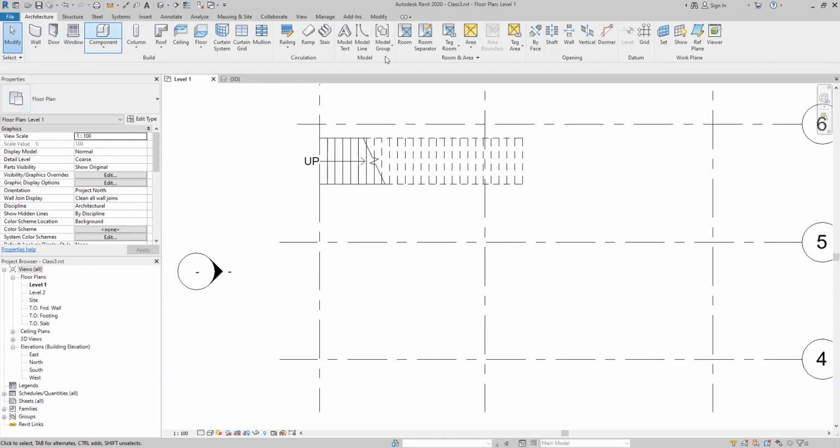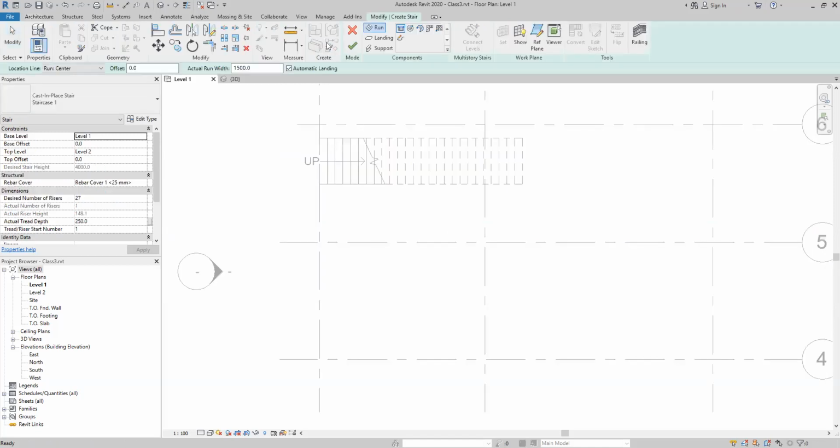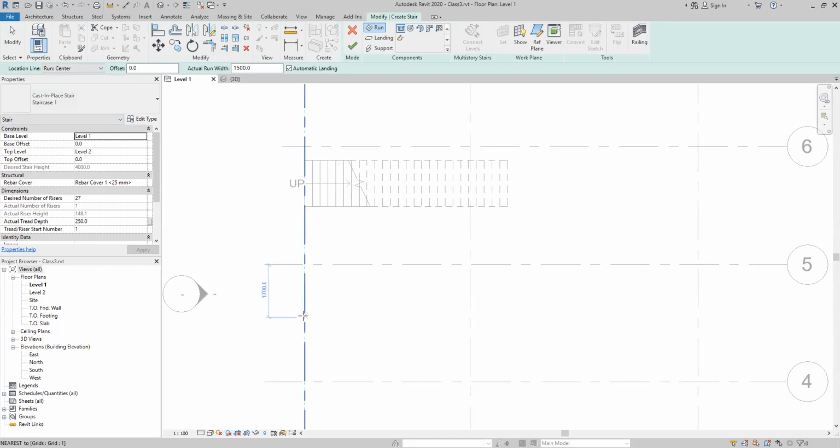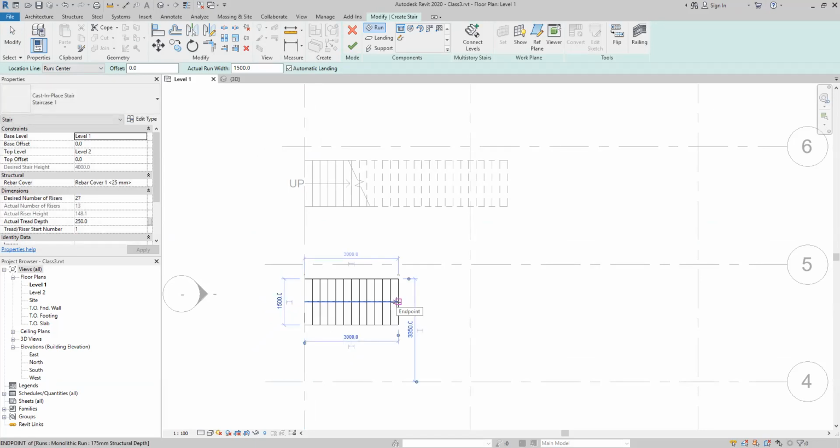Okay. Go back to the staircase. Click staircase. I am going to follow the same thing, staircase one, right? Same property. I'm not going to change the property, same property. So now I wrote my central line of the staircase here, right? I go to the first level. So I decide first level is 13 steps. So I stop with 13 steps. So this is first level. Then now I had to set up my mid landing.